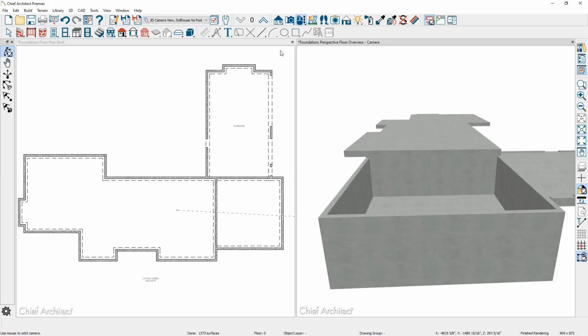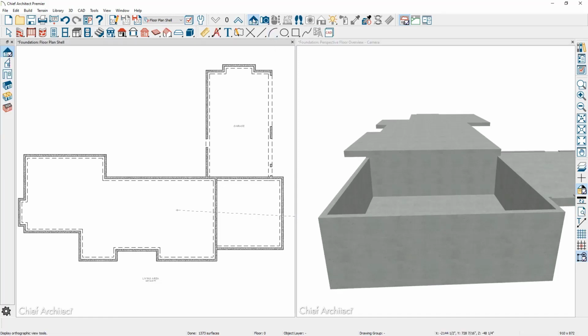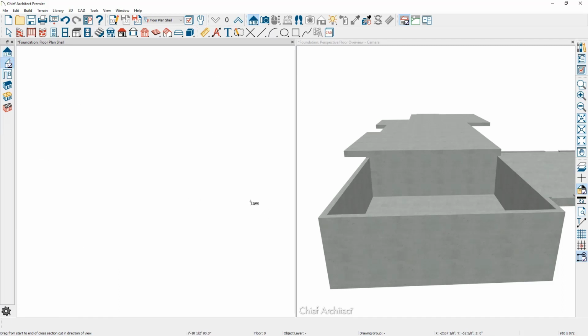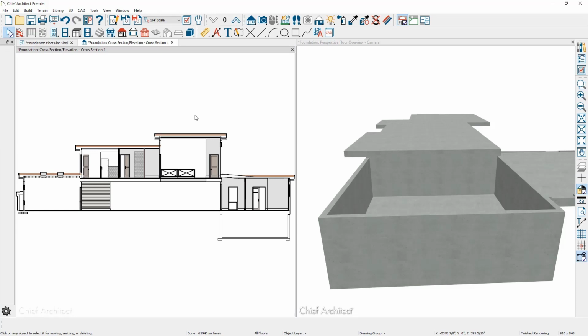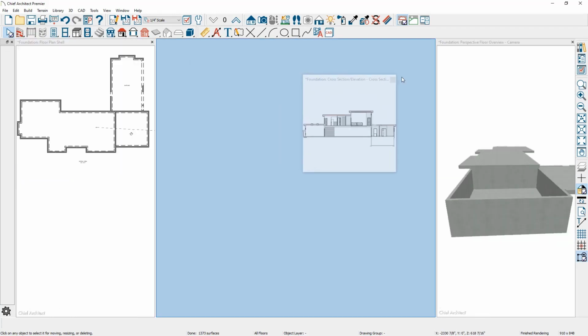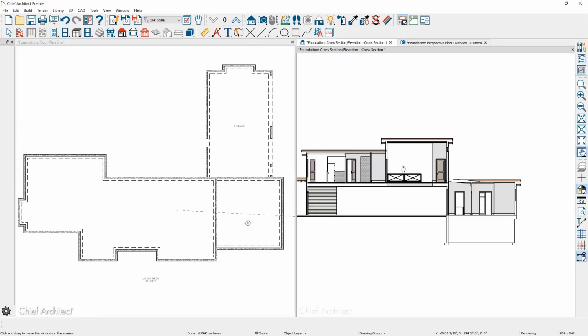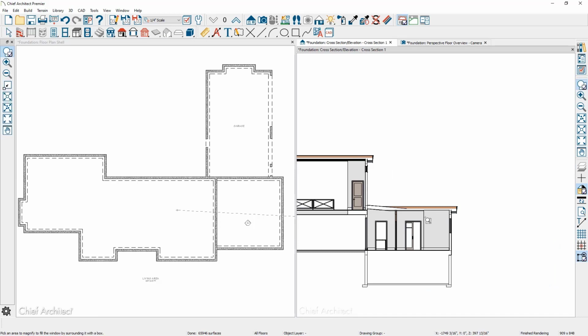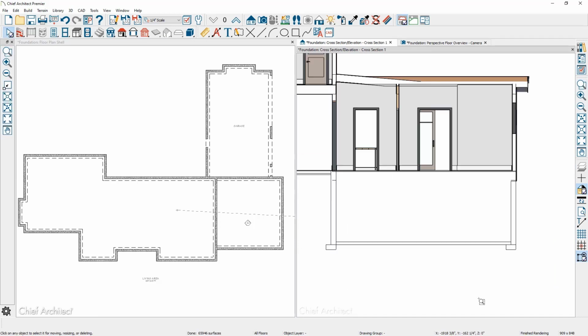To do that, I'm going to move over into the floor plan view. Let's use our cross-section camera view. Actually, the back clip. We'll slide the clip through the area. I'm going to pull this view over, slide that over here, and then use the zoom tool so we can see exactly what we're talking about for the foundation. You can see the walls have an offset for the footing. Let's begin there and center the footing.